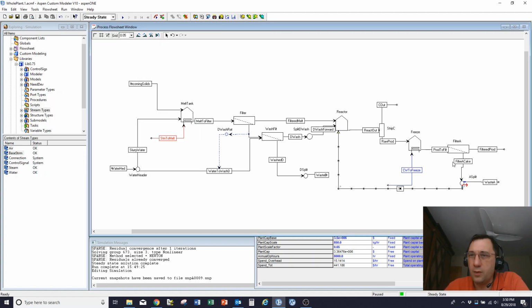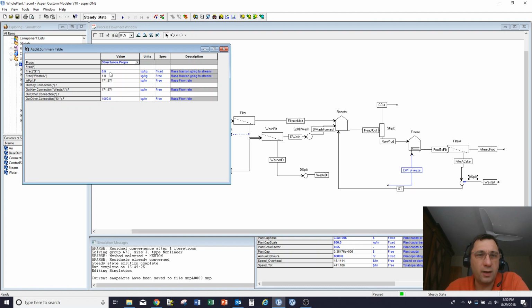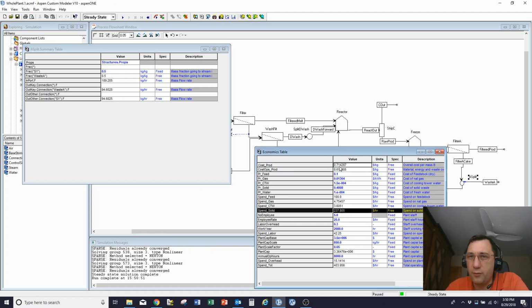By default, that splitter sets it up with 50% recycle. Let's make sure that that runs. It does. You see I've gone from 80 something back down to 70 something. Why am I recycling 50%? That's just the default value. I could increase that as far as I like. I could presumably recycle all of the material.